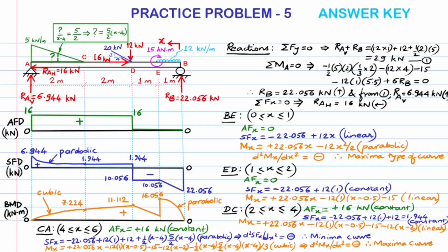Welcome back again. Here the reference end is taken as the end B only for the sake of convenience of calculations. It is simpler to represent the part of the uniformly varying load at region AC created by a section by only one term, that is by a single equivalent point load if the reference is taken as the end B from where the variable x is measured.